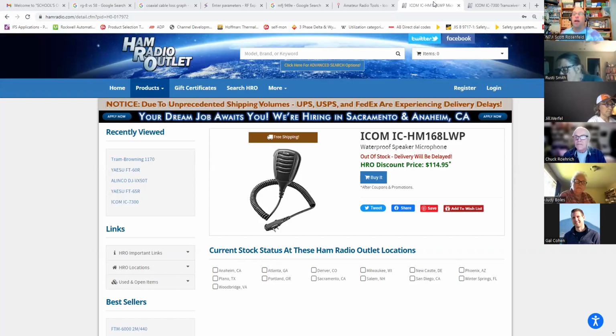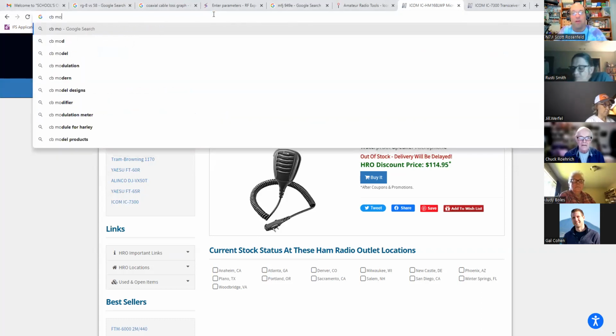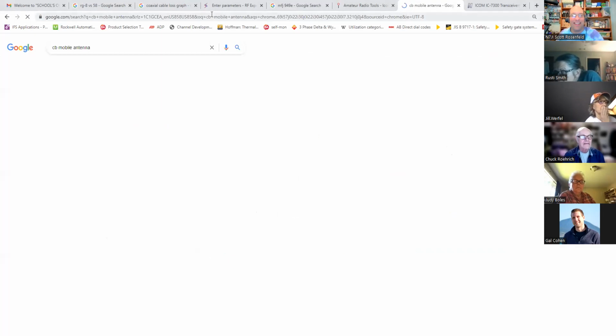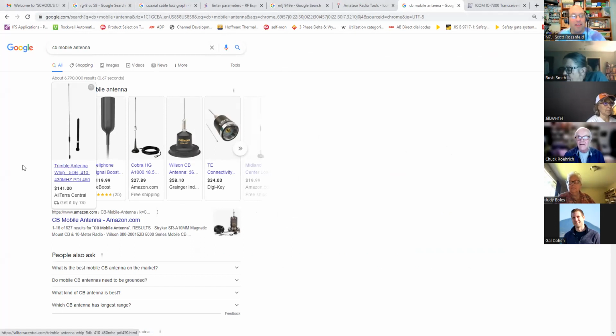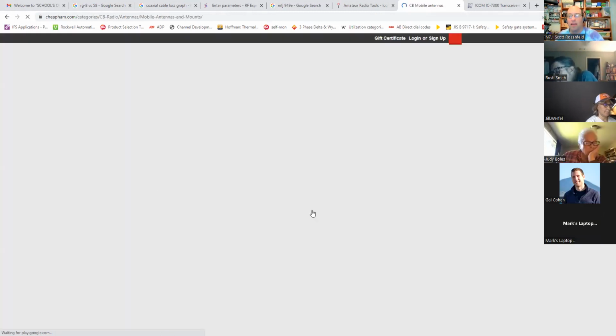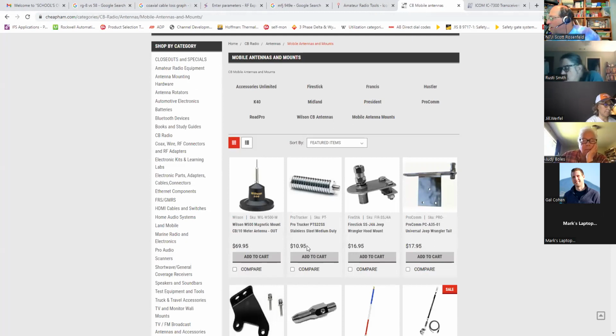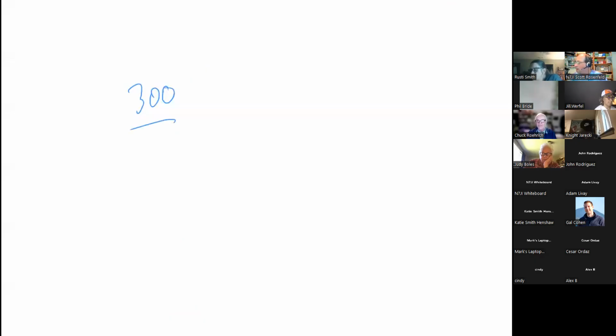Okay, but now we know why it's a 102-inch whip, don't we? Why? You tell me. If I tell you Citizens Band operates at 27 megahertz, you can tell me why it's a 102-inch whip. I know I should know. Well, I'll give you a hint. It's 11 meters. 300 divided by 27.2.